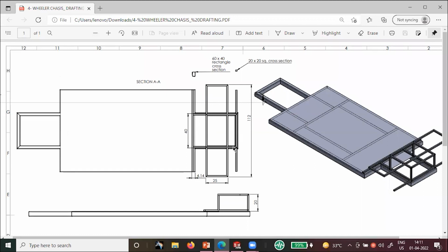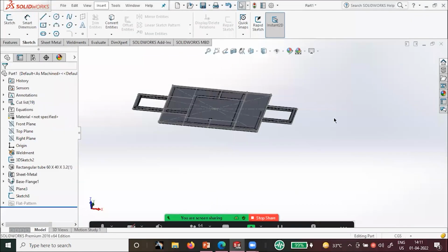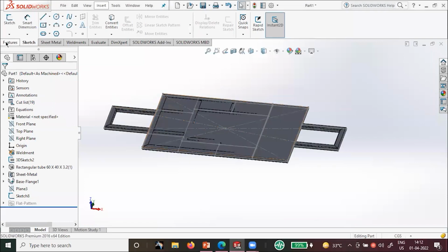That should be simply from here to here that we convert entity, create a line here, create a line here, and that we need to box. That box should be a 20 distance, the upper side profile is 25, and the distance of this rectangle is 112. Let's do it. Go for here, switch again, select the 3D sketch. Go to the sketch option, expand, go to 3D sketch. Now it has selected 3D sketch again.